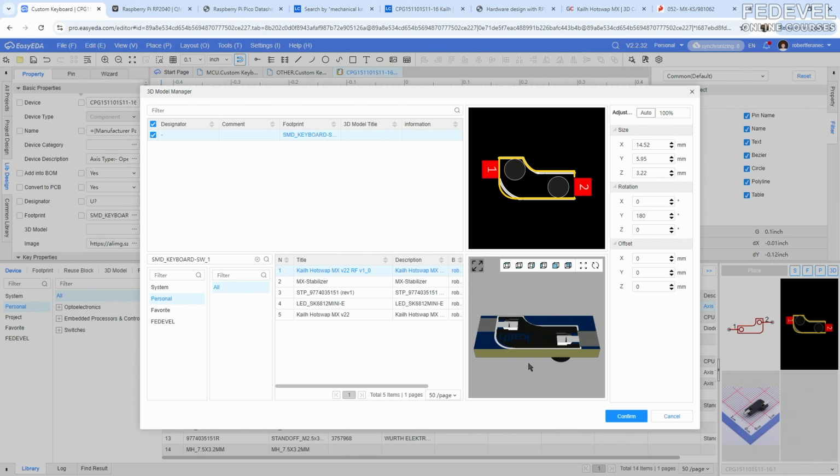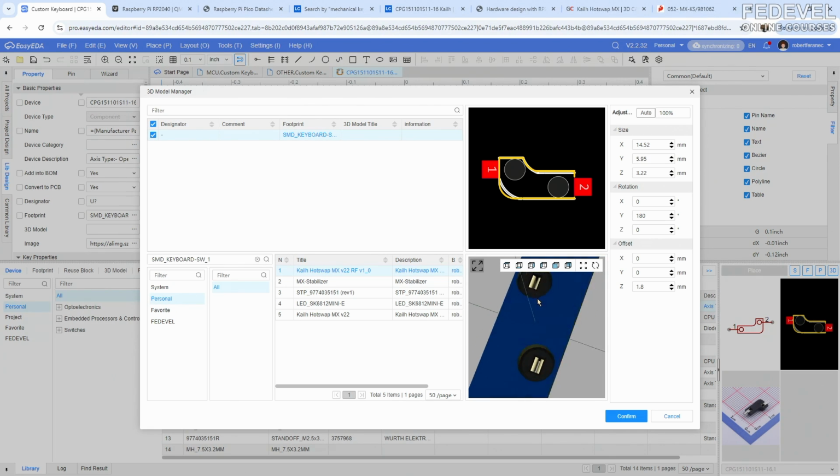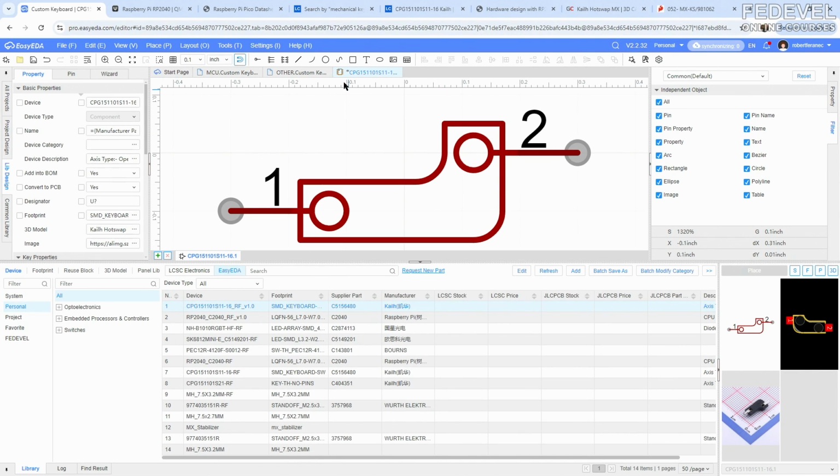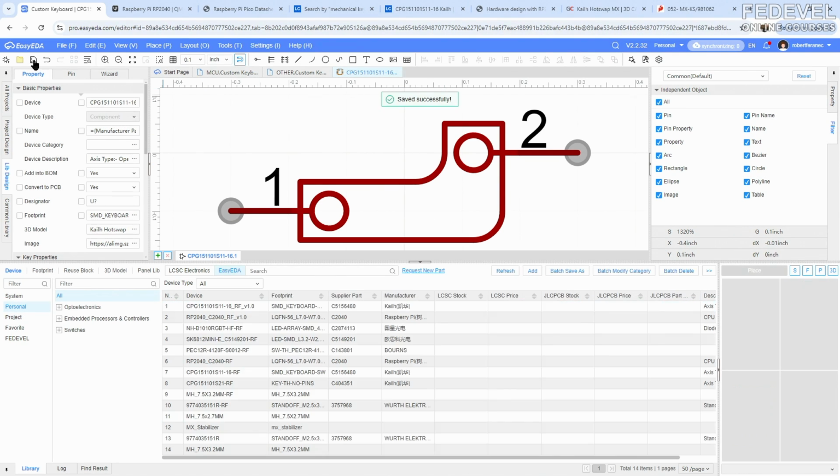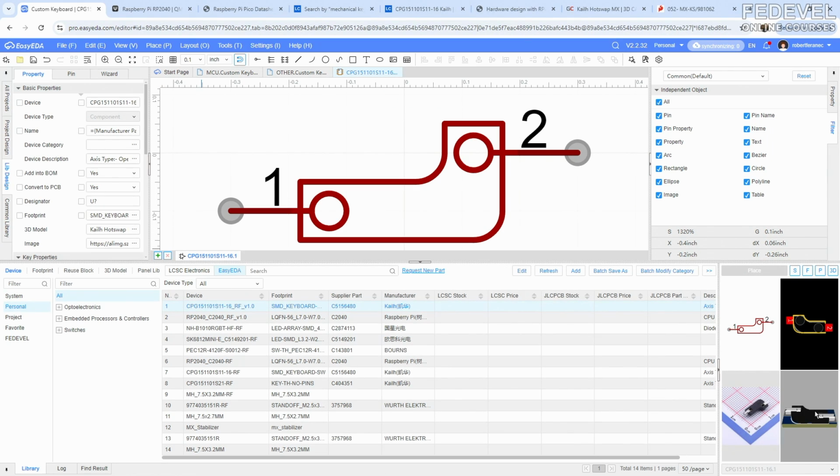we corrected the footprint. So I'm going to place the 3D model exactly as it should be placed. So it's upside down. And be sure the pins are placed correctly on the pins of the footprint. This looks good. This looks okay. And perfect. Now it's finished. We can save it. And when we double check the 3D model, here it is.